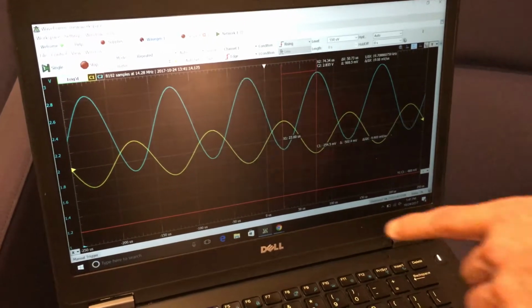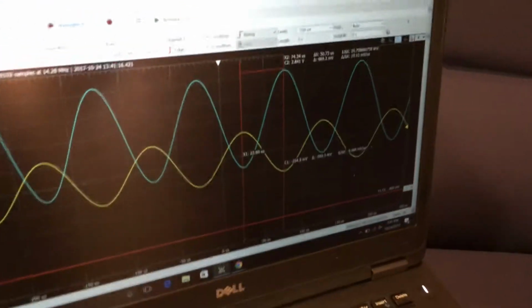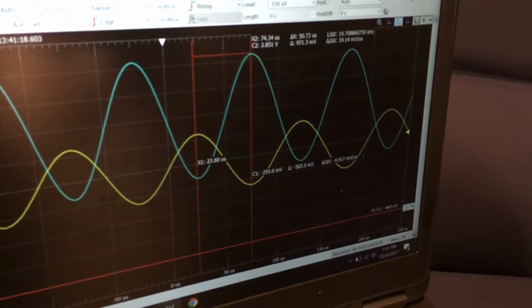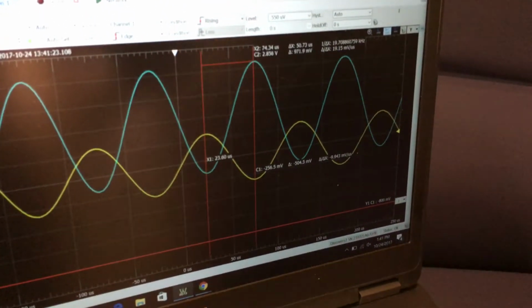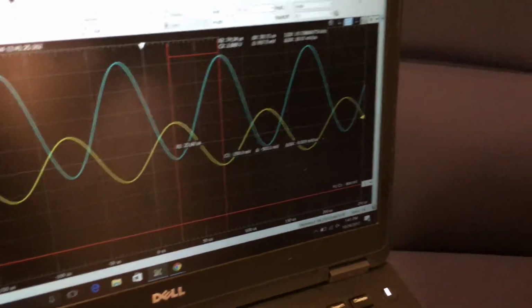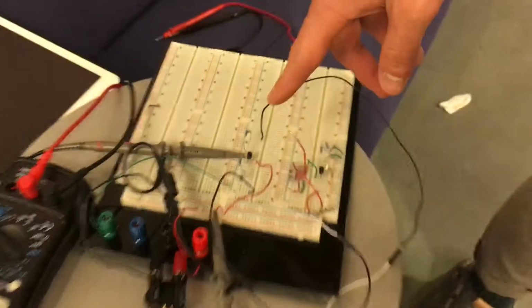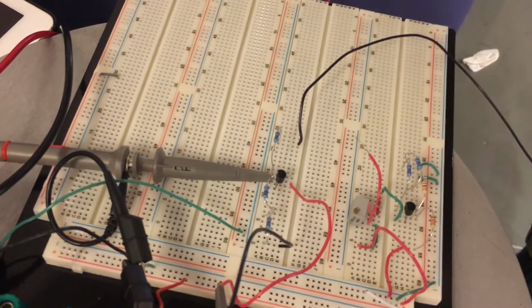And there's a DC offset as well, which just comes from the VBE value of our circuit, which is about 0.7 volts. And then the gain for this part of the circuit over here is negative 2.